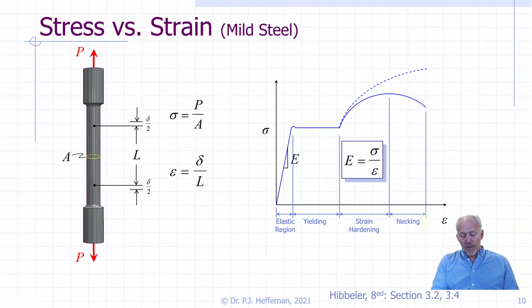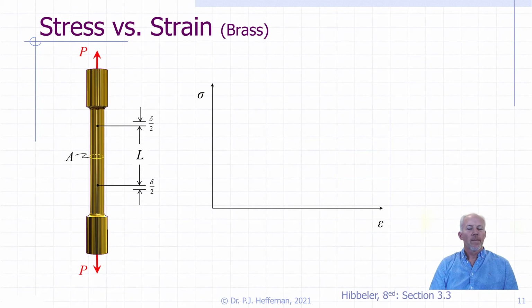Quite often, too, we will use what we call a strain gauge. A foil strain gauge is applied to the surface of the material, and as it elongates, we measure the resistance through the gauge itself. And of course, as it elongates, the resistance goes up. So we're able, again, through a calibration, to understand what the strains are that are going on in the material, averaged over the length of the strain gauge itself. It is worth remembering that we can't actually directly measure stress or strain. Those are calculated from other observations.